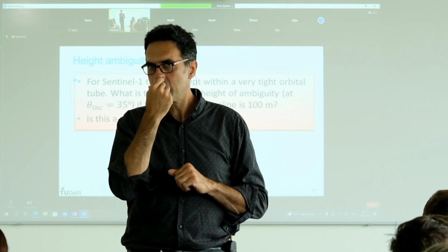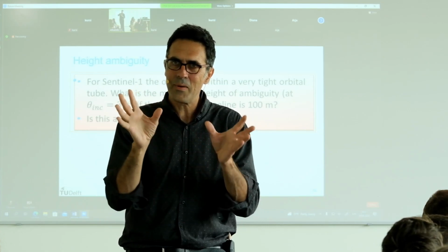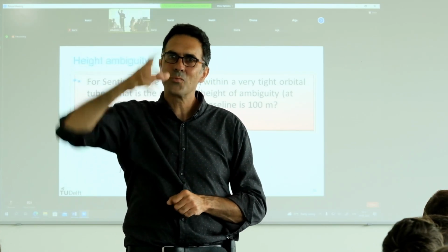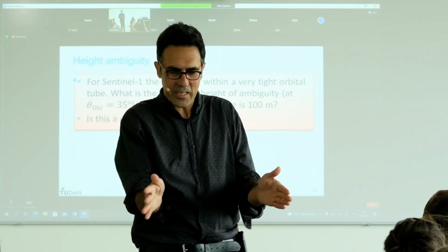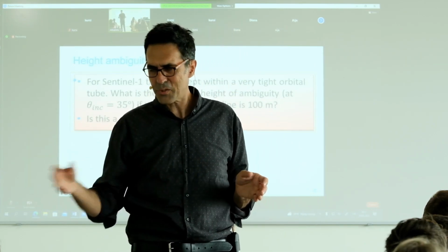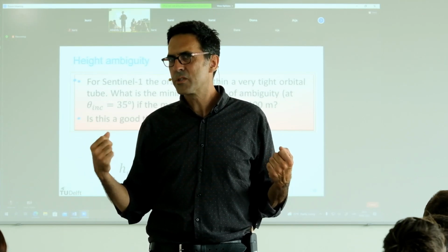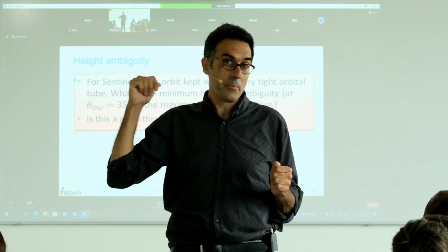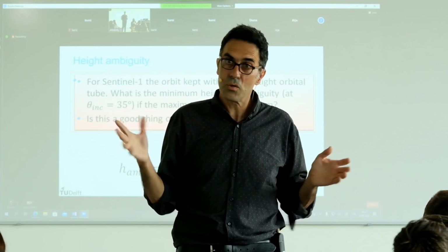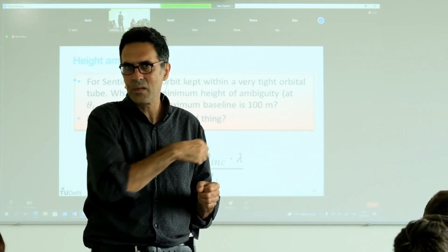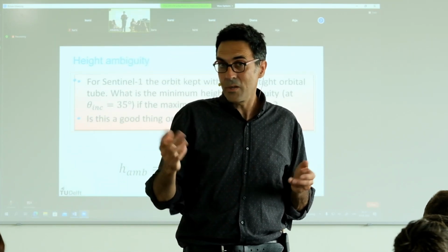For the example that I showed you in the beginning, of this little building that has ghosts, remember? That is where it didn't go well, because this antenna also has side lobes, so there's also a little bit of sensitivity there and there. So as long as the reflection is not extremely strong, it's okay. But that particular building was accidentally so strong that it was also picked up by another one. So in those cases, you get errors.